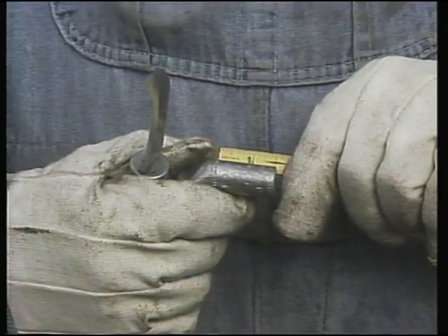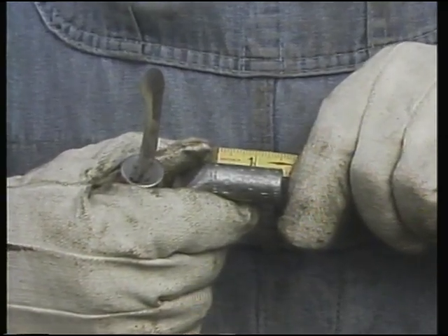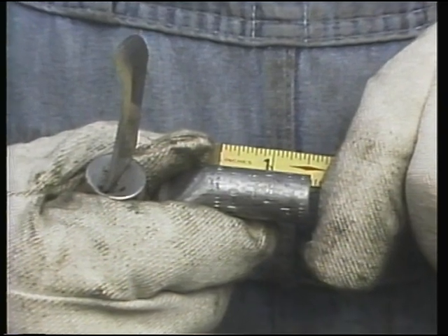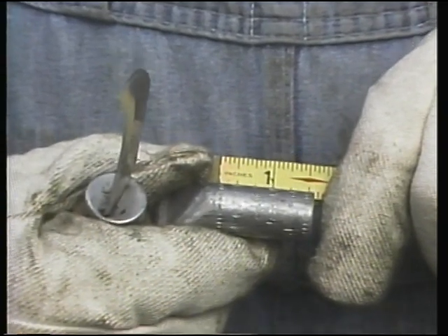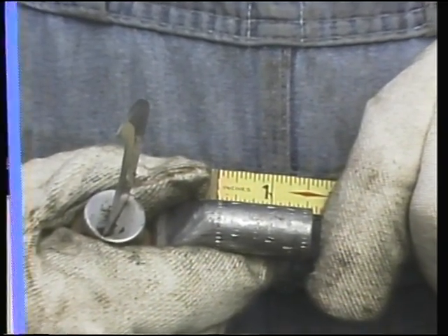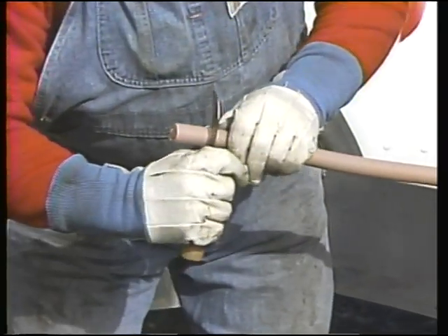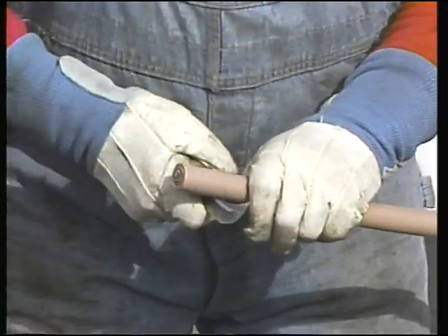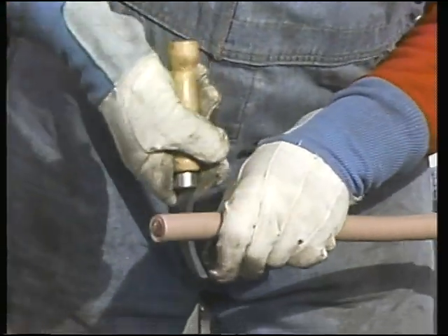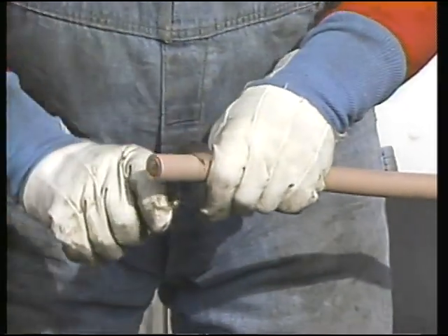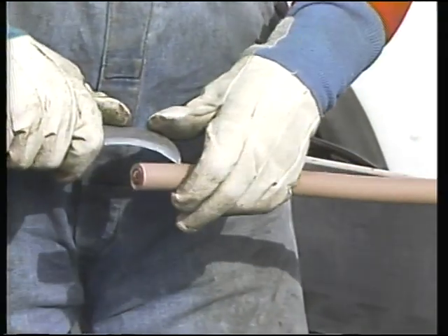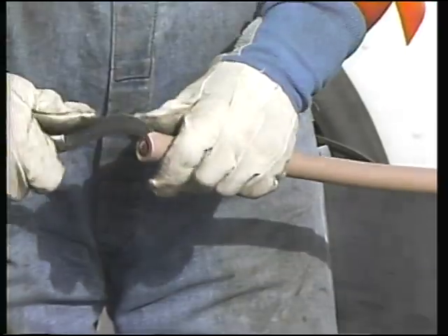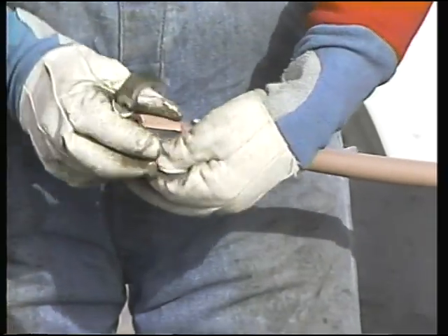Often, the amount of insulation that has to be removed to install the connector is indicated in the instructions. If it isn't, you can measure the connector first and then measure the cable. Then the insulation and the semiconductive conductor shield are cut. Care should be taken not to nick the conductor with the cutting tool. After he makes the first cut, the workman makes a second cut lengthwise back to the end of the cable, and then removes the insulation and the conductor shield.